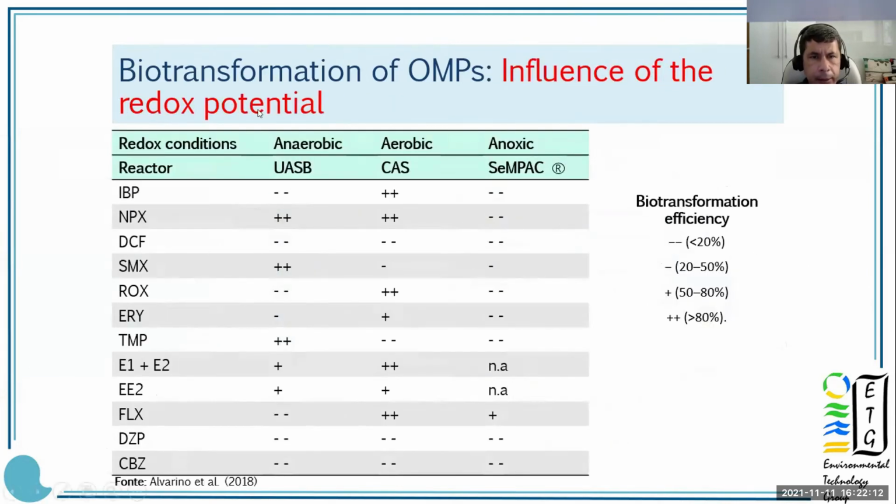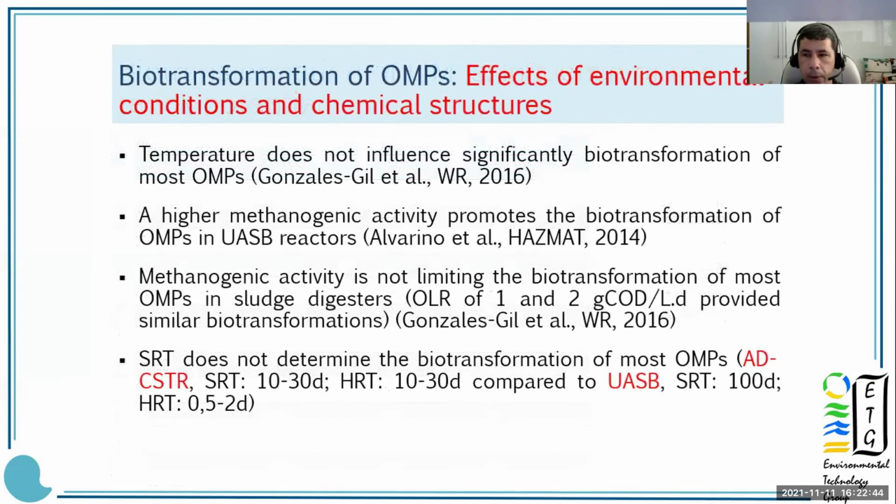Here we compare the removal of some micropollutants under anaerobic, aerobic, and anoxic conditions, and we can see very diverse removal of the compounds across conditions and structures. Therefore, it is very hard to establish a pattern and comprehend the full picture of micropollutant removal in treatment plants.